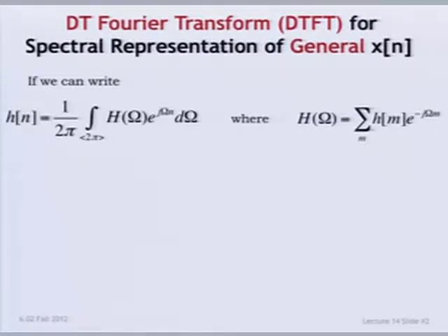You've seen the definition. If I give you the unit sample response of a system, you know how to compute the frequency response, and then we went through how you can go the other way with the DTFT to compute the frequency response and the inverse DTFT to compute the time domain signal from the frequency response.